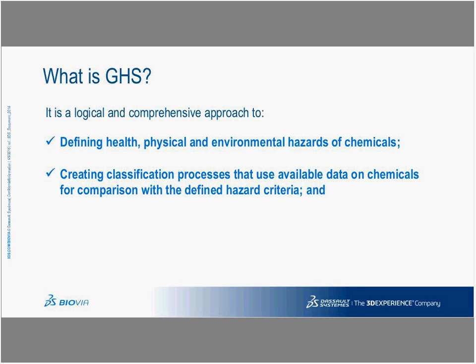It really looks at a couple of key characteristics, things like flash point and vapor pressure. But that's a US-based classification system, so that when we look at butane, we know it's highly flammable, a rating of 4, for example, versus a 0, which represents something that wouldn't burn. So that's how we do it, but it's done differently around the world. Everybody has their own types of classifications. So with GHS, the goal is to come up with common criteria to define those hazards.